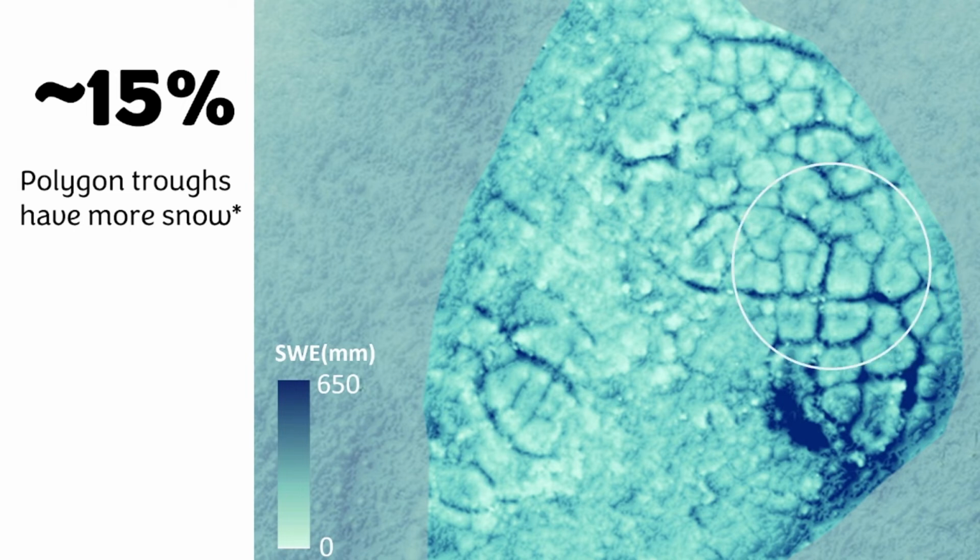However, I should mention that this is probably an underestimation here because there's also vegetation within a lot of these troughs, and that's something that's very hard to filter out in the digital surface model. So we might actually see larger quantities of stored water in these troughs. Now we tried to mitigate this by editing the point clouds from the drone data, but you can't simply remove all vegetation. So we might have a little bit of an underestimation there.